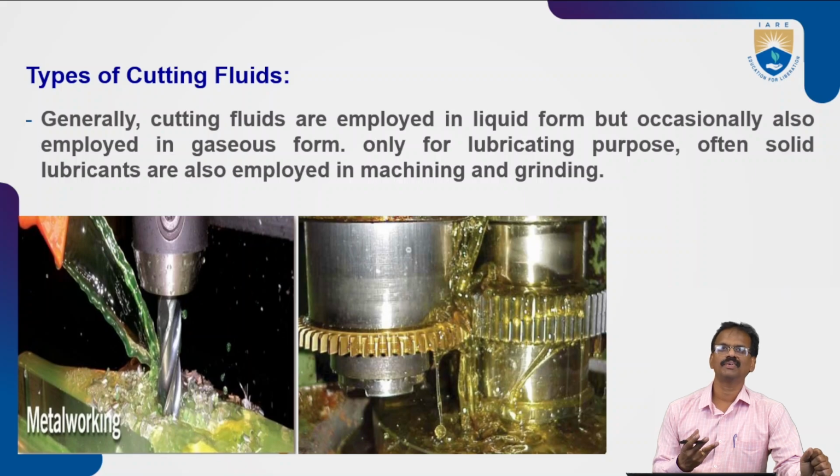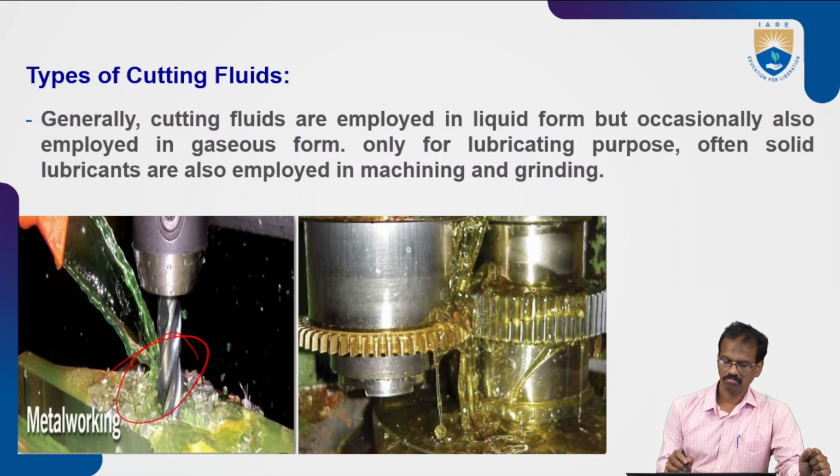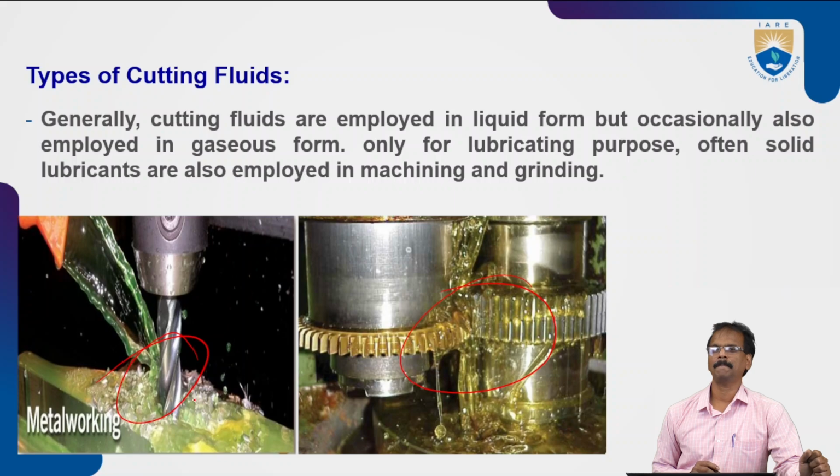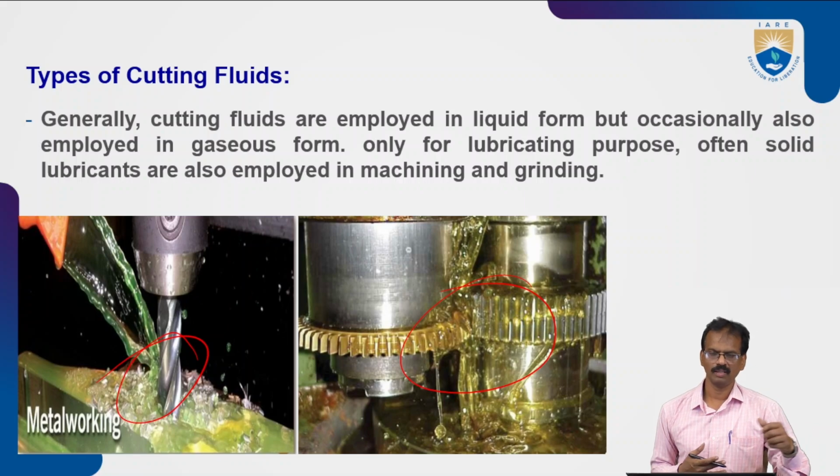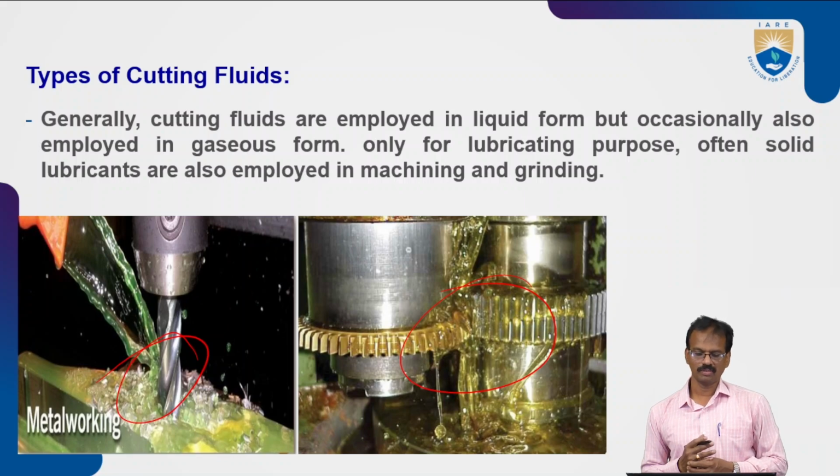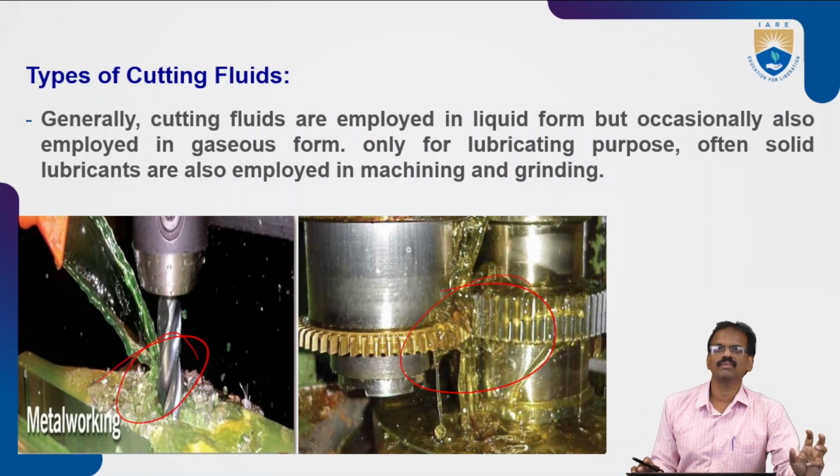One is the liquid type, another one is gaseous type, and then one is solid type. Here, liquid type and solid type, just a gummy type, and we can use the argon and carbon dioxide also, and air, natural air also. We can use those fluids or air gases for the cleaning and machining, cleaning the interface of the tool bit and the workpiece.